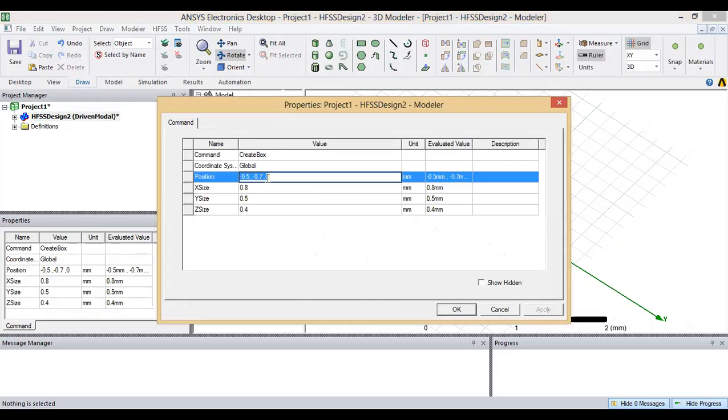Here, let's say I need a box having length 20 millimeter, width 10 millimeter, and the height should be 5 millimeter. Positions means we can assign the position in different ways. Either I can design at 0, 0 and 0, which means x axis is at 0, y axis is at 0, z also at 0. I mean from the center it will start designing.